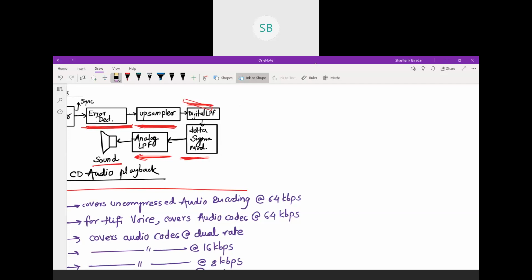The error control is exercised in the following way. First of all, a parity digit is employed to correct the error that occurred. If a certain bit is incorrect, then it is simply inverted to carry out the correction. Otherwise, if there is sufficient redundancy in the code, then we can use this redundancy to determine the correct data value.